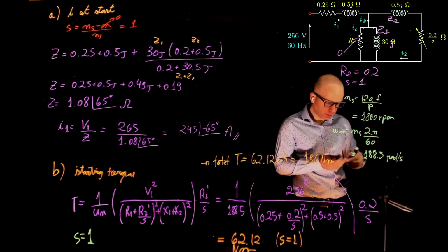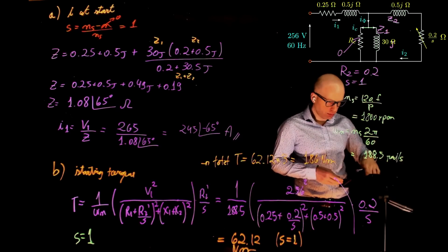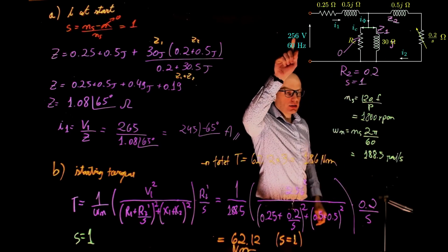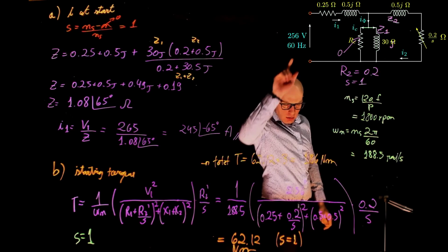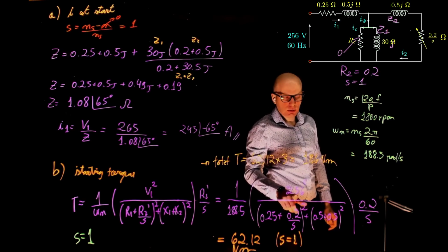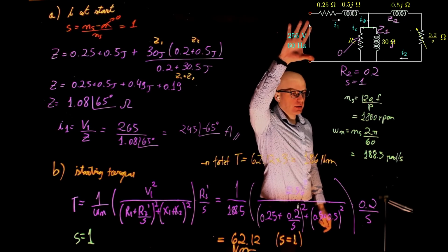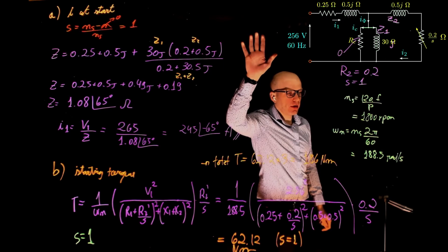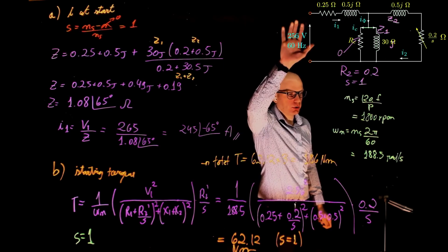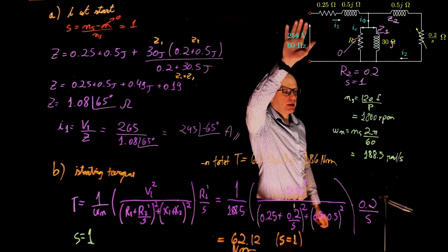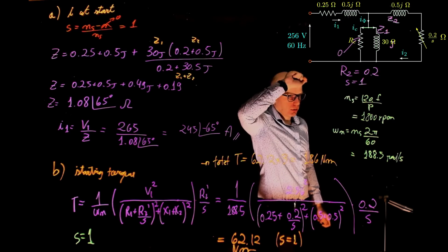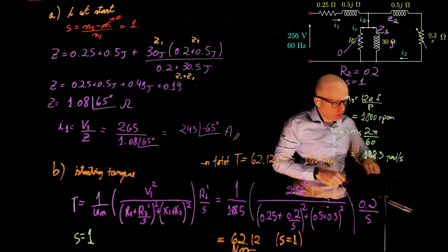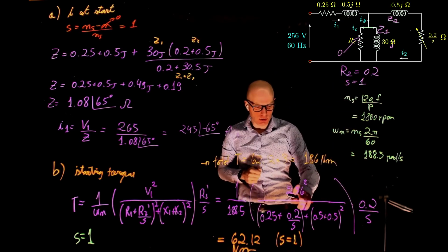Sorry, you said the estimate shows the voltage as 265 instead. Just a note. Yes, this is the 250. Oh, did I? 256. Oh, this voltage is the line-to-line voltage. The 460 is the three-phase input voltage. This is the phase voltage input. That's phase to phase, and this is phase to neutral. Sure, it just says 265. Oh, okay, that's more accurate. And let's do 265. Thank you.